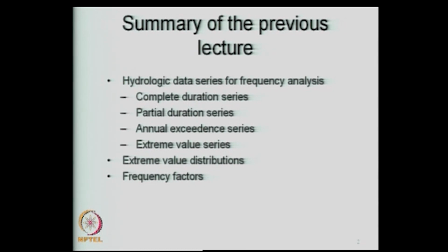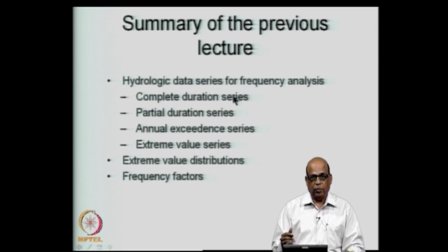We may use the complete duration series, where the entire available data will be used for the frequency analysis. Let us say you have monthly data for the last 40 years, all the data will be used for the frequency analysis. In such a case, the series that is used is called a complete duration series.